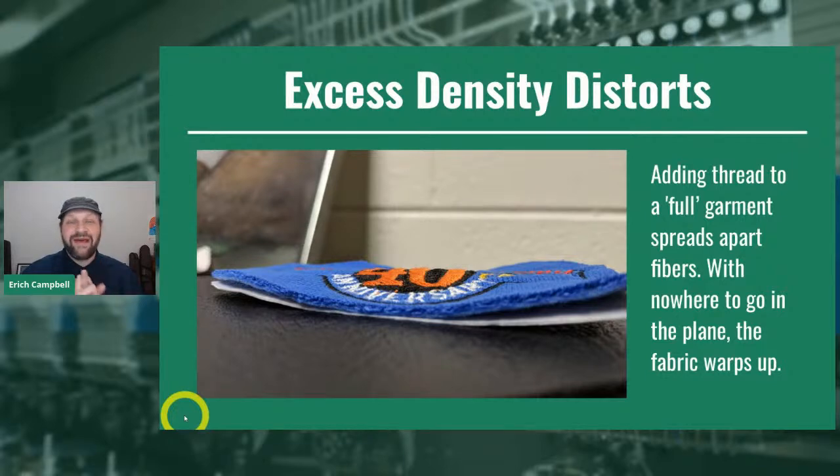Number one, when we have a bunch of needle points all landing in the same place, we can get thread breaks, especially layer after layer. And if we have a bunch of density already in place, more than the coverage we need, and we start dropping stuff on top, we can get thread breaks, we can get distortion there, and we get those, like I said, those bumps and lumps, and that's from thread building up. The other kind of distortion is this.